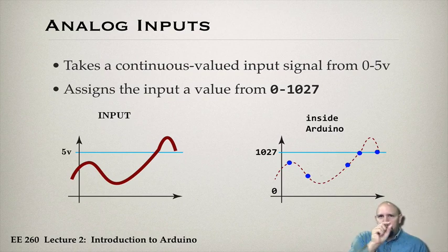In other words, I grab these at very specific values in time. I only know the value of the process at the time that I grab it. So when I grab a value at this point here, just by looking at that value, I can't tell whether the original signal was going up, going down, at the top, or staying constant.